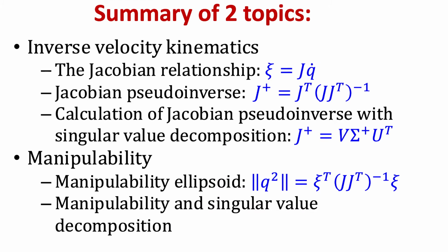Now this slide has just about all the math that we're going to need today as we talk about inverse velocity kinematics. We're going to learn about something which is called the pseudo-inverse, because we want to invert this Jacobian, but sometimes this Jacobian is not an invertible square matrix. And so we need a different trick to do that. And so since we can work on the right side because we're controlling our joint velocity, we need something that we can insert on the right side. And so that is the right pseudo-inverse.